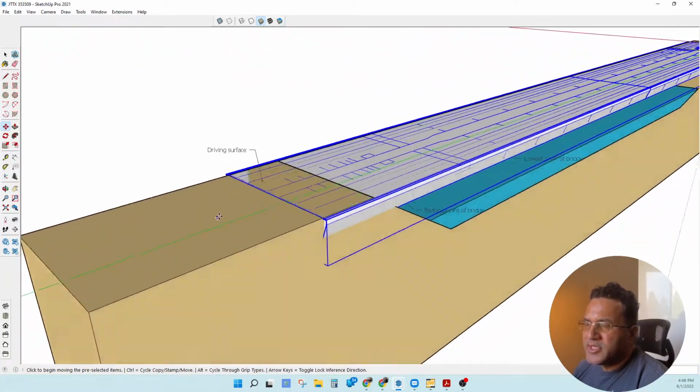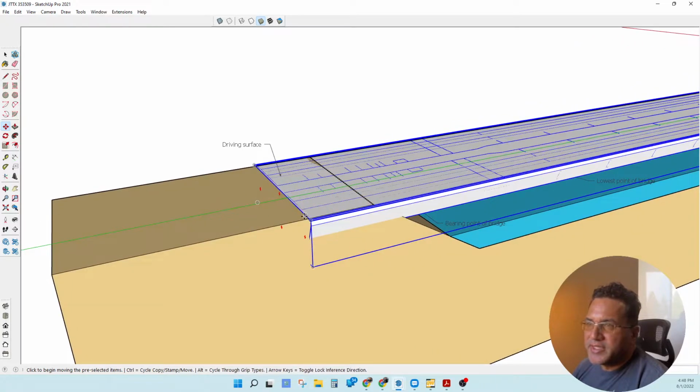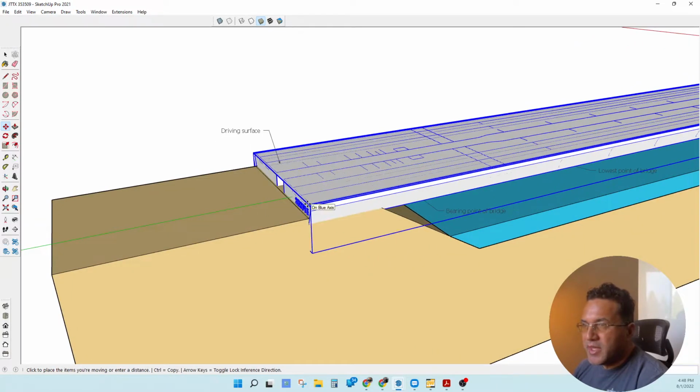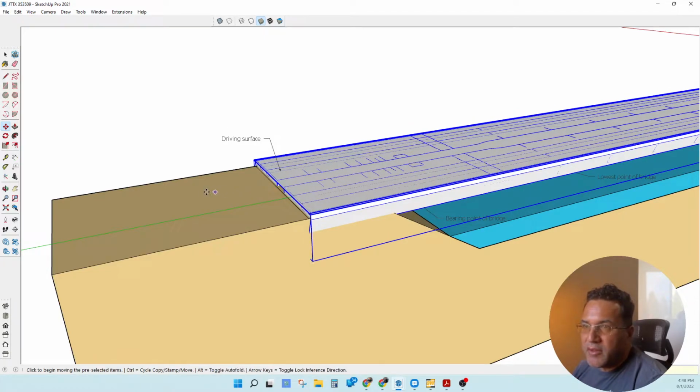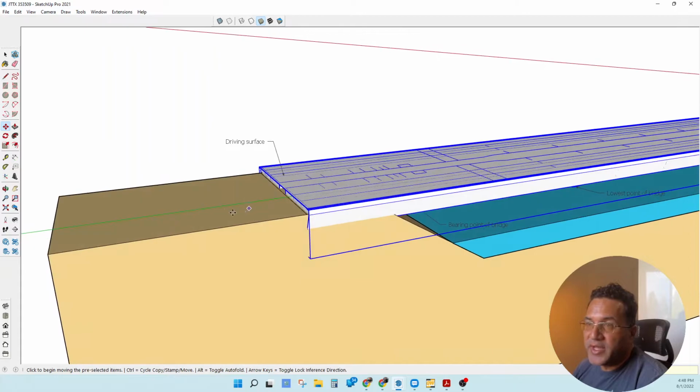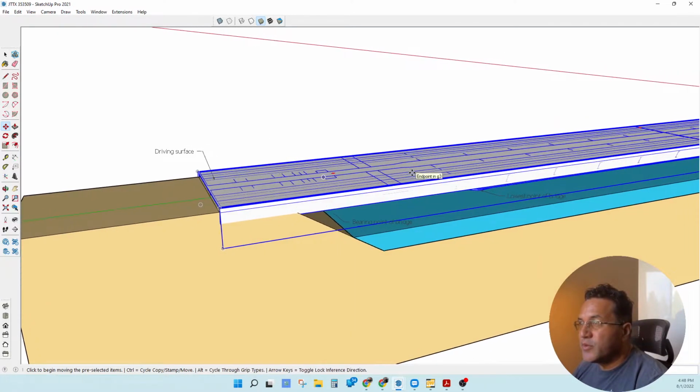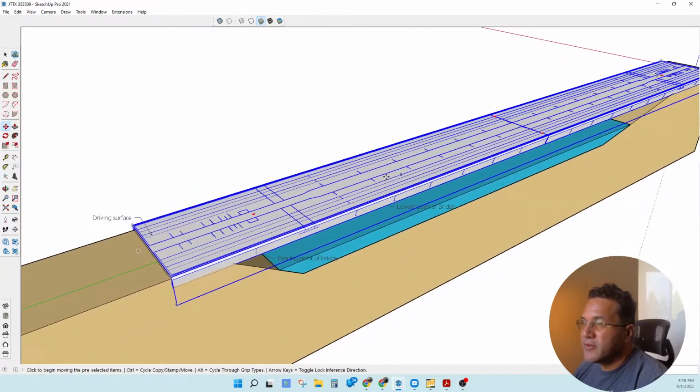over. Now, typically, if you're going to do this, we would actually raise the bridge up just a few inches, maybe like 4 inches, so that way you can put gravel on the roadway over here, and then you have a smooth transition. So you have 4 inches of gravel over here, then the bridge would make a nice, smooth surface all the way across. Okay. Now,